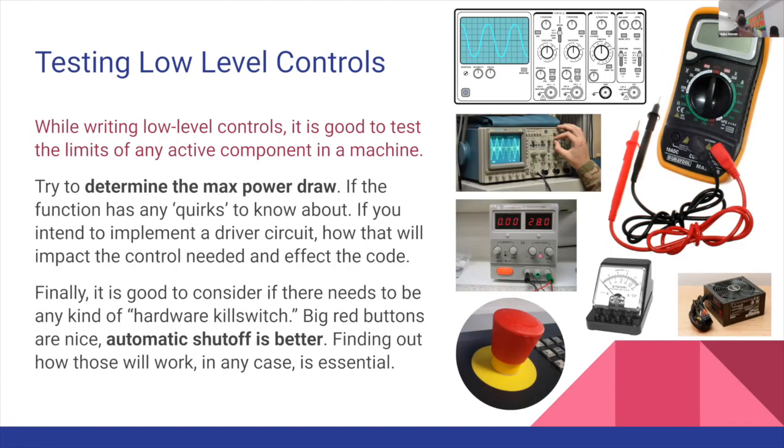And so while you're doing that, the automatic shutoff is better, I want to say. This is implemented in all current 3D printers. All of them have an automatic heat cutoff. And if you don't have a thermometer, the 3D printer will often yell at you and say, I don't actually want to operate. It'll send error messages saying you don't have a thermometer on your hot end, so we're not going to print anything until you've replaced that. It's a very common problem because those wires are delicate, so they can die.